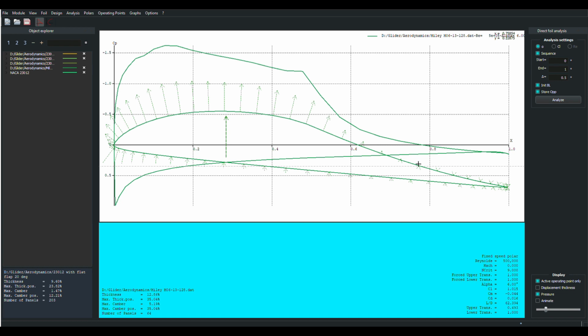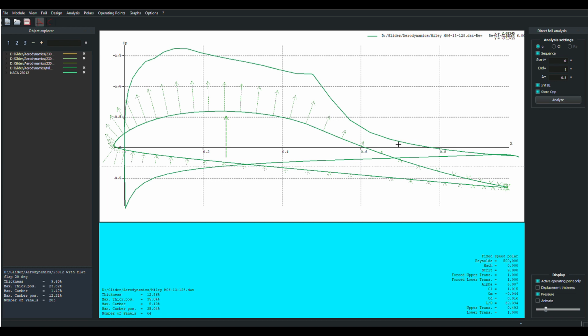And we see there's no hump. Because this is a rooftop pressure recovery type airfoil, they're called that because this kind of looks like a rooftop here. And then you get to where they trip the flow right here, and whoop, very rapid pressure recovery, as fast as you can without separating the flow. And then it starts to go out pretty flat. And there's not much happening back here. The adverse pressure gradient beyond about 60% of chord is minimal at best.